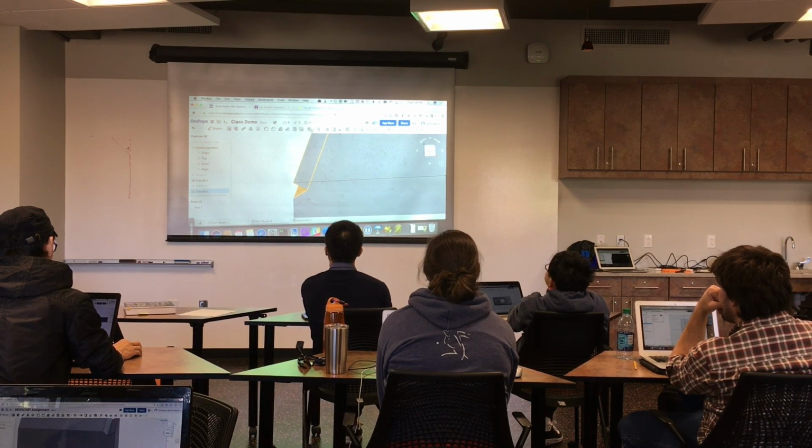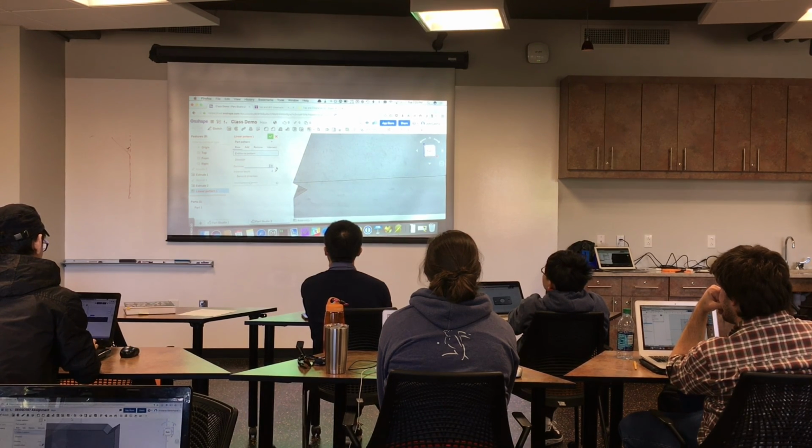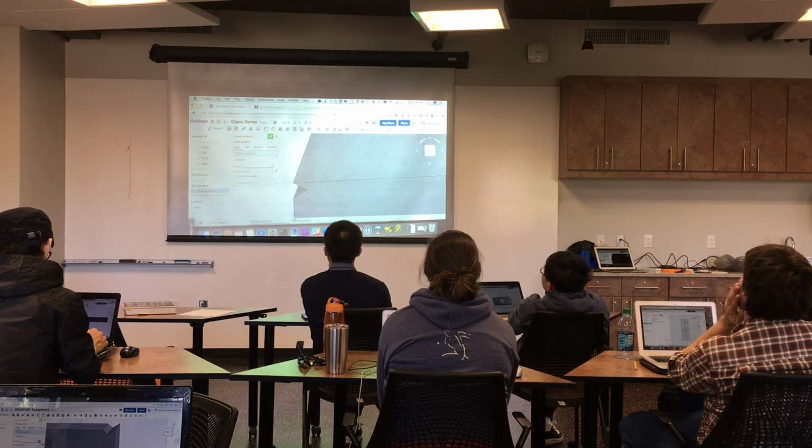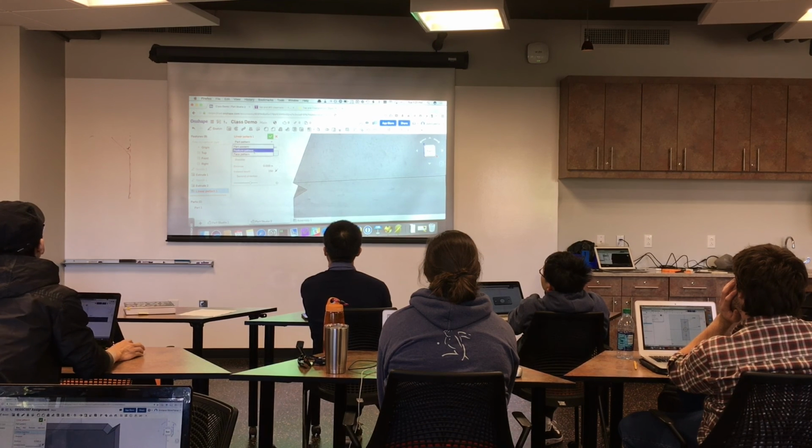So I'm going to take that extrude, and up here is a pattern. I want to make a linear pattern. I want them to be 1 millimeter apart. I want there to be 150 instances. And we need to pattern a feature. I'm going to pattern extrude. In the direction, you can just select this line here. I want to pattern in this direction. And it's working.